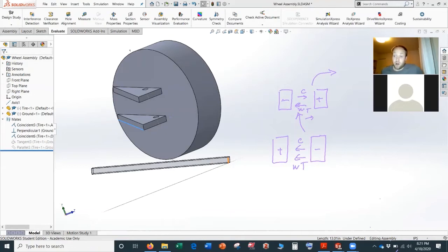So for Baja, we've talked a lot about how doing this will help put weight on this wheel and kick it around. I'm not sure if that's necessarily the case. I think it's more that it pins this front right wheel on the Baja car, and you have so much weight transfer in the rear that you begin to have a lot of oversteer and begin to lose grip in the rear. And that's why you spin around this front wheel, which helps in these tight turns